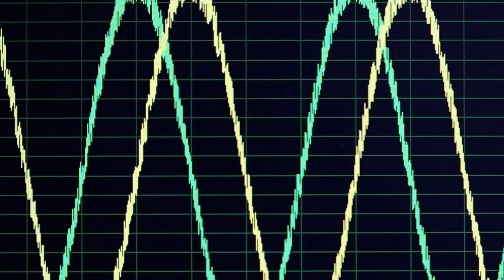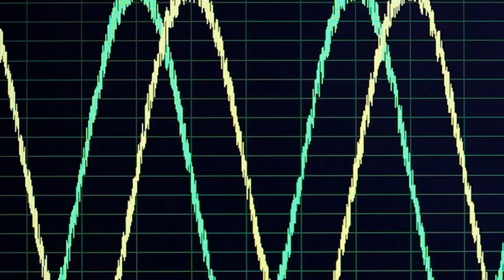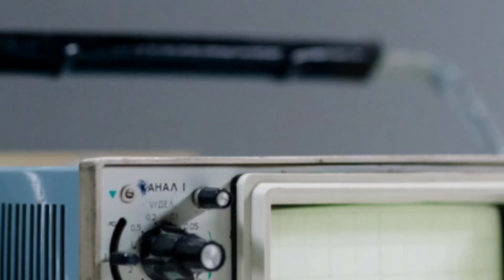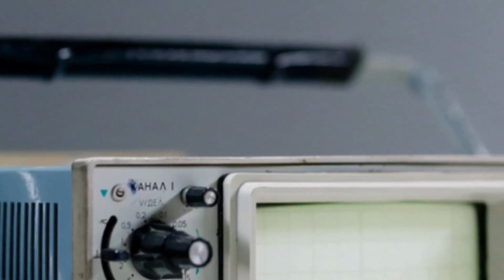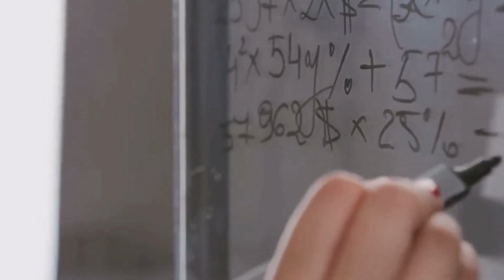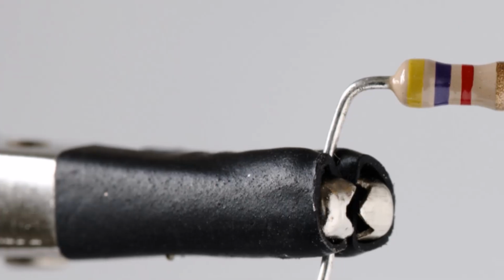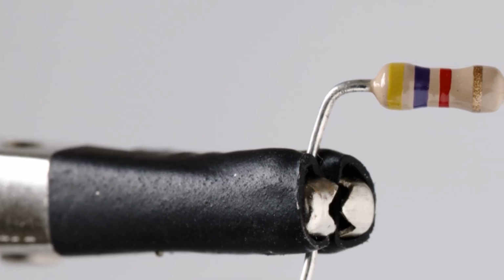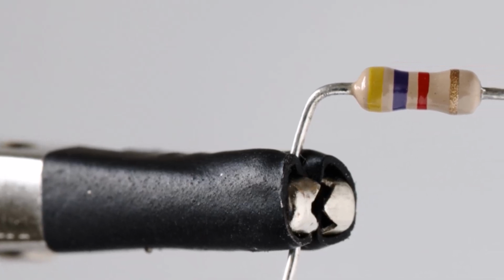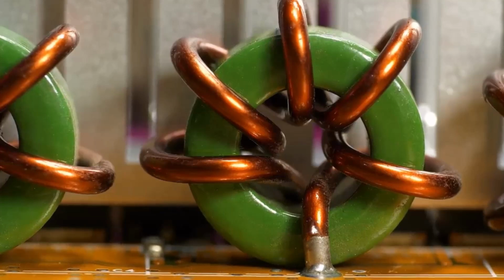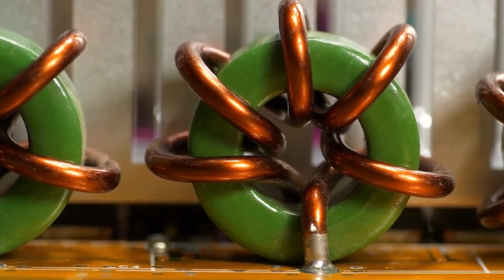In an AC circuit, the inductor causes the current wave to lag behind the voltage wave. This creates a phase difference, and our simple Ohm's law doesn't quite work. But with phasors and complex numbers, we can handle it with ease. First, we represent everything as a complex number. The voltage source has a magnitude and a phase, so it becomes our first phasor. The resistor's opposition to current, its resistance, is just a real number. But the inductor's opposition, called reactance, is an imaginary number.